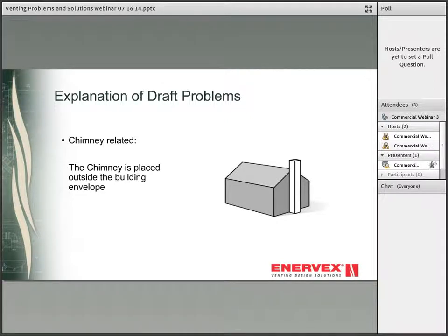If one or more sides of a chimney are exposed to the outside, the chimney can experience excess cooling, which will reduce the draft. The chilling effect can be so bad that the exhaust gas is not able to create any draft at all, at least not during startup. The best location of a chimney is within the building, so only a very small part of the chimney is exposed to the outside.